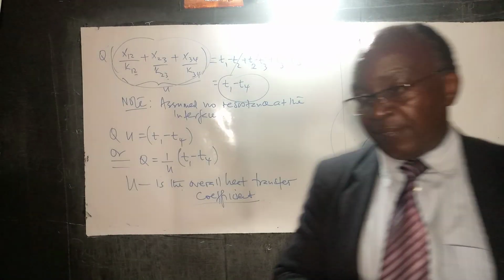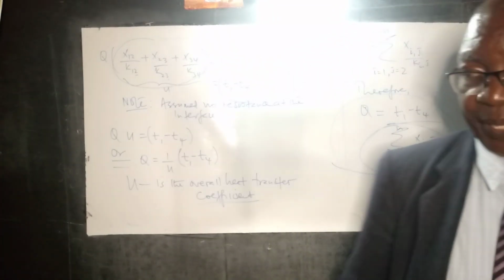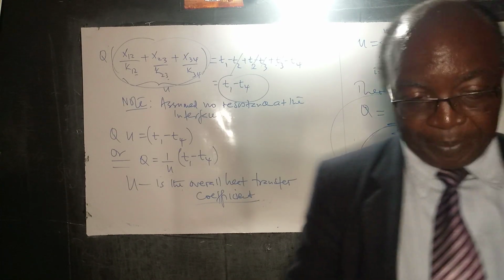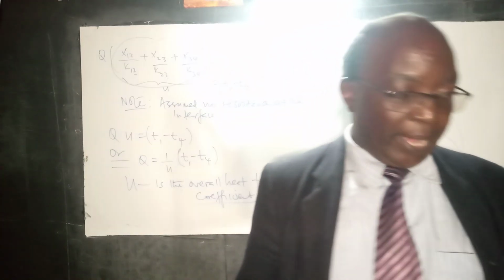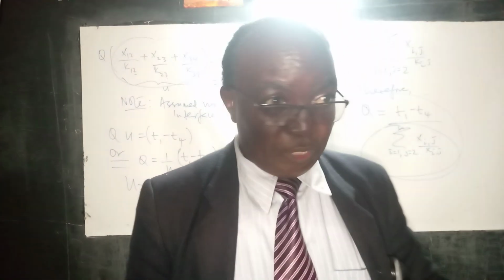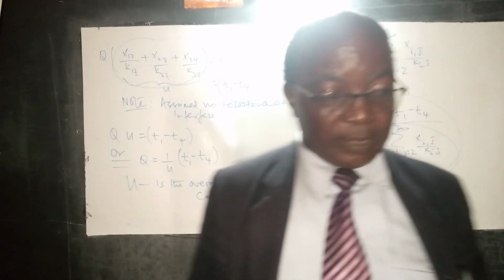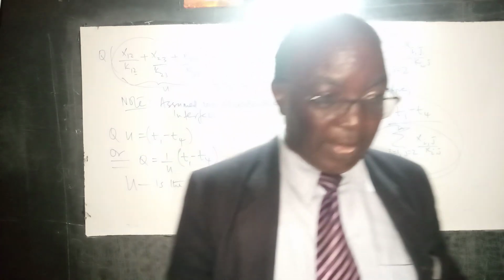Simple. We have made several assumptions. One, we are assuming that the walls are isotropic. In other words, the material properties of that particular system are uniform. It's also isothermal, not for the different walls, but for each wall. And then the rate of heat transfer is uniform throughout that particular material.